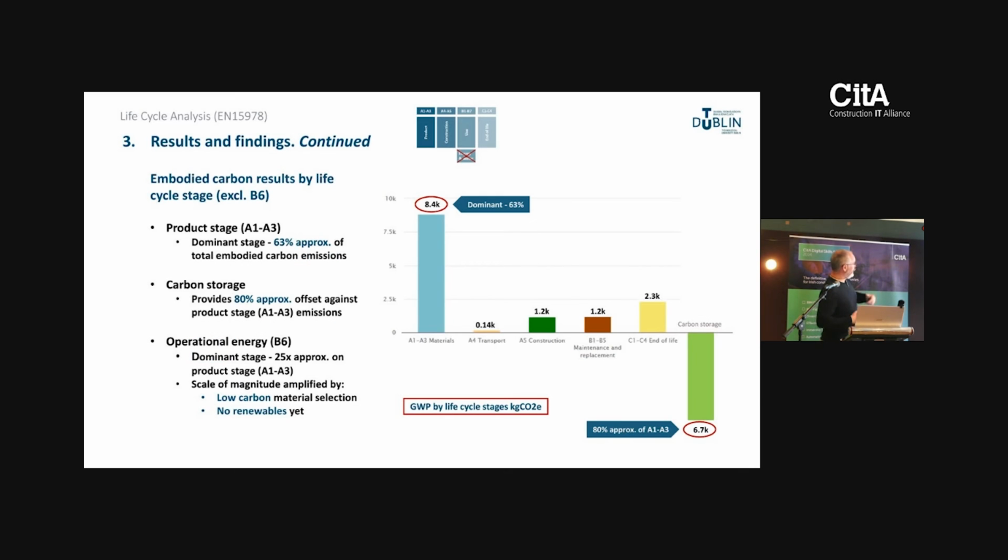But what's really interesting here, we used a limecrete slab. We didn't use a concrete slab. 100 millimeters of NHL5 limecrete with polymer fibers to increase the tensile characteristic of that slab, on top of expanded glass aggregate, foamed glass aggregate. So 300 mil compacted to 250 and another 300 mil compacted to 250, because the void was there. The floor void, including the slab, from the floor finish to the original underfloor, was 600 mil.